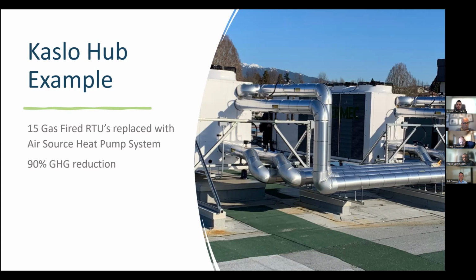So we put in a new hydronic system with 4 pipe fan coils serving all the spaces, and then 2 AirMech air to water heat pumps producing both hot water and chilled water. So these are 4 pipe air source heat pumps with a chilled water buffer tank and a hot water buffer tank. So there's always hot water and chilled water available.